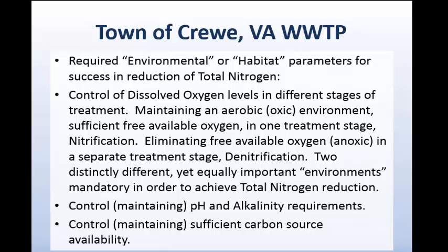You have to control and maintain pH and alkalinity requirements, and they're very specific. During the nitrification stage, pH and alkalinity control is critical. And those two parameters can either enhance the process or they can limit it. And in extreme cases, extreme swings in pH and alkalinity can actually stop the process.